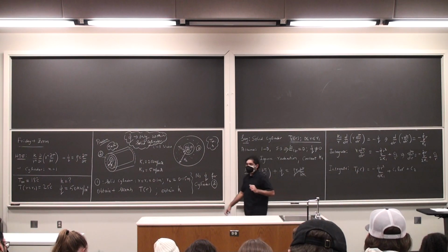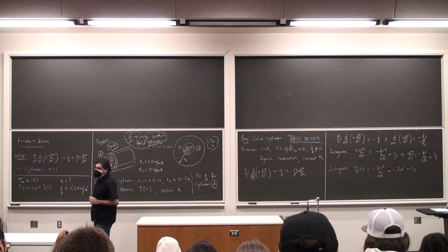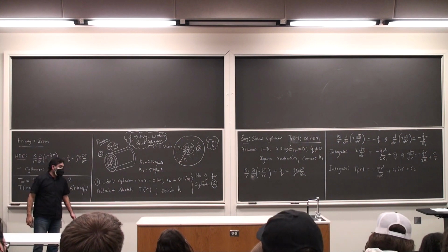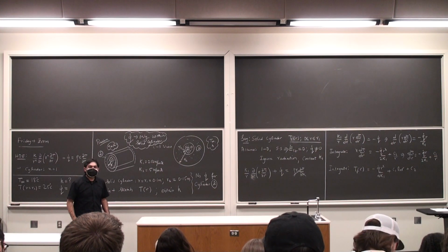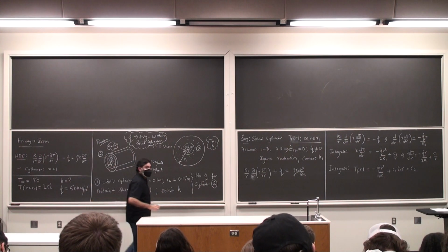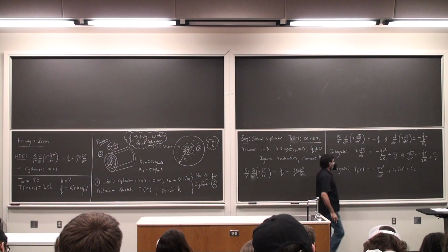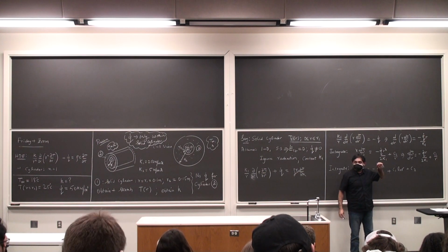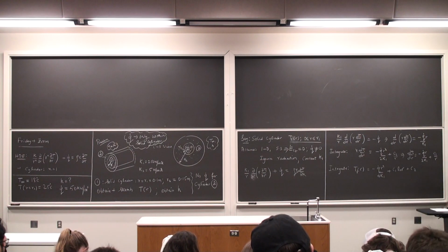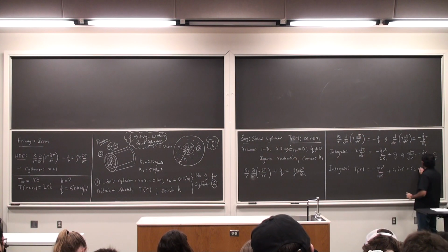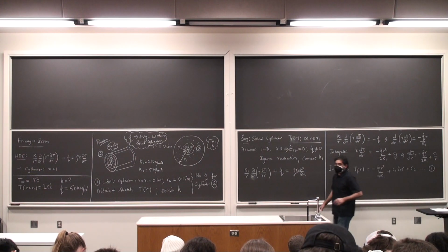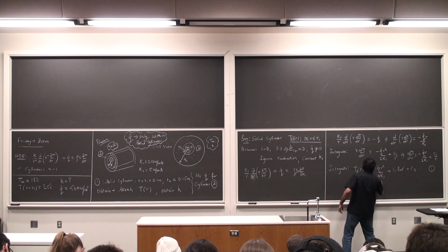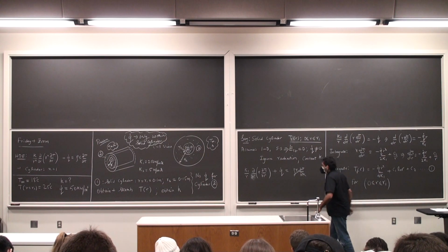What are the units for the natural logarithm? So ln r, logarithm of r, what are the units? It is dimensionless. So this does not have a unit, which means that C1 is going to be in degrees Celsius or Kelvin. C2 is also going to be in degrees Celsius or Kelvin, depending on what you're operating in. Okay? So this is equation 1. Set it aside. This is for that particular range of r.